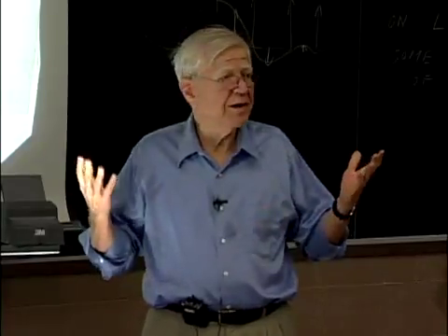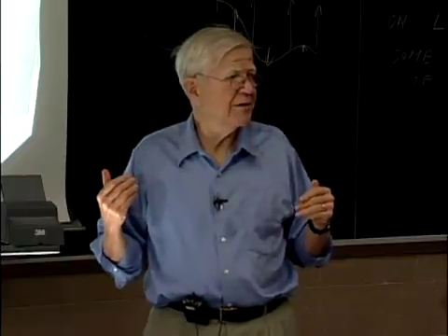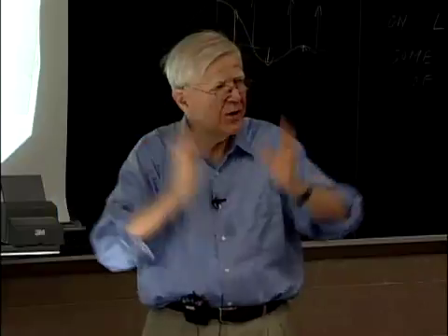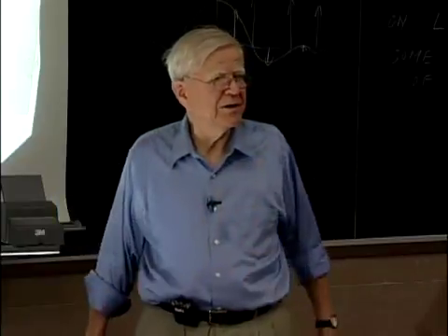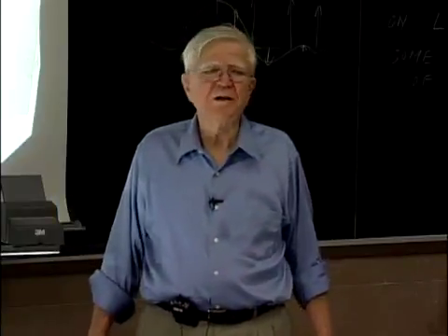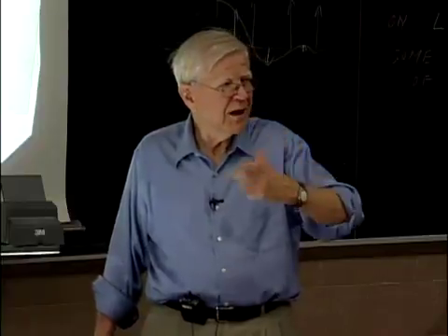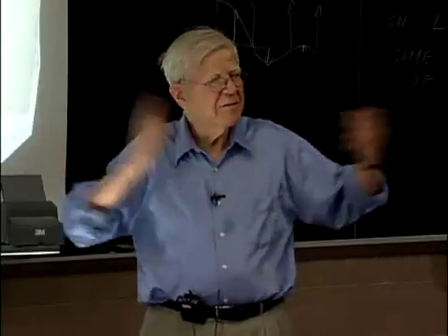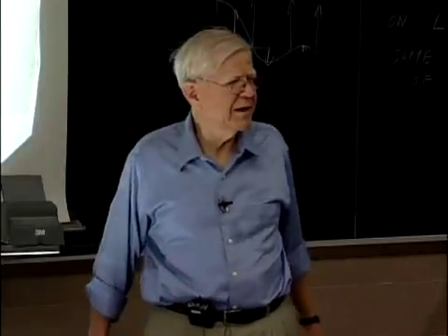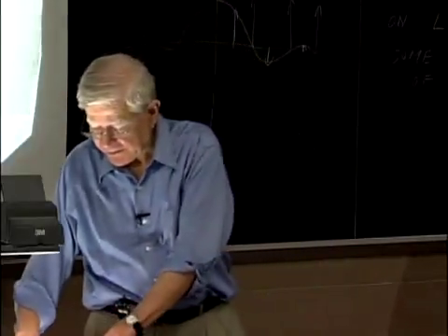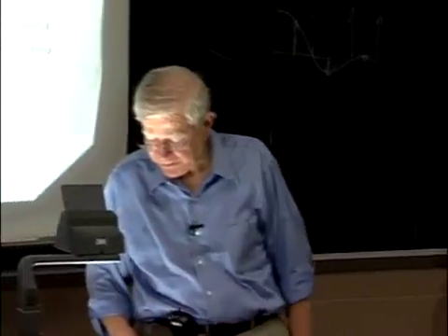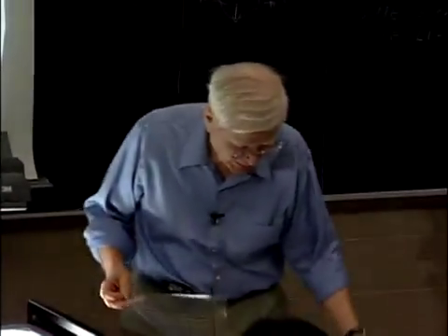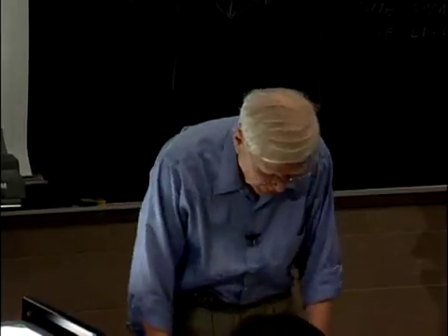Now you see why you have the scrambler in here, why you have the interleaver. You have the interleaver to take these highly correlated errors coming out of the rake receiver, where blocks of 6 errors tend to appear together, and you scramble them out so they're widely separated, so that the Viterbi decoder is able to deal with them. So that's the last piece of the whole thing.